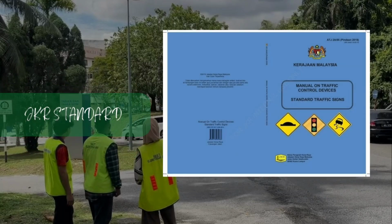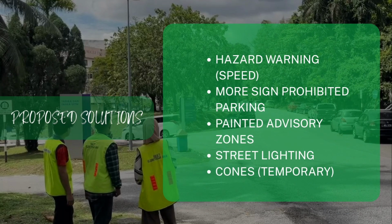For this problem, we can use JKR standard, which is standard traffic signs. Proper solution is putting a hazard warning for speeding, more signs for prohibited parking, painted advisory zone, street lighting, and cones for temporary use.